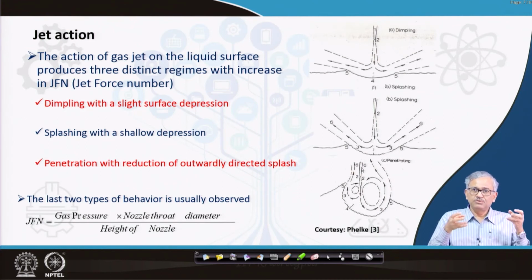You build up the FeO by suppressing the decarburization, and this is mainly done when you have a large amount of impurity like phosphorus in the liquid iron. So what you have to do is continue with the carbon to the end of refining. In that case, initially you do some soft blowing such that you build up the FeO, because the FeO buildup is very important for the CaO, calcium oxide, dissolution.